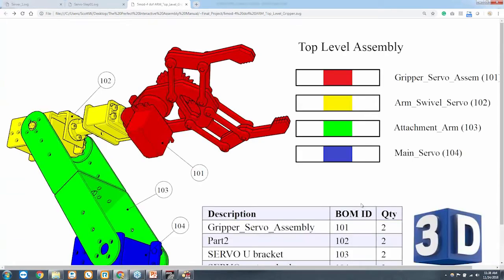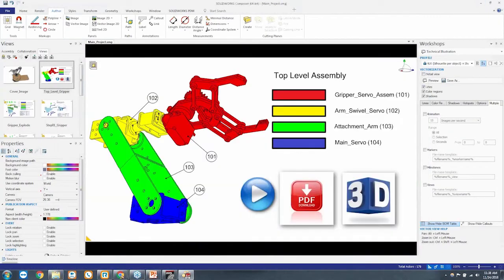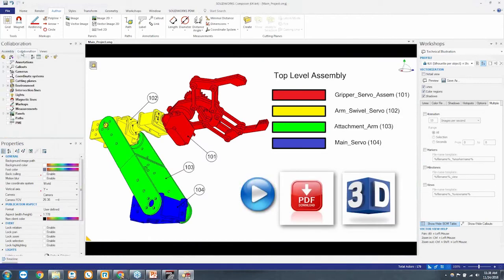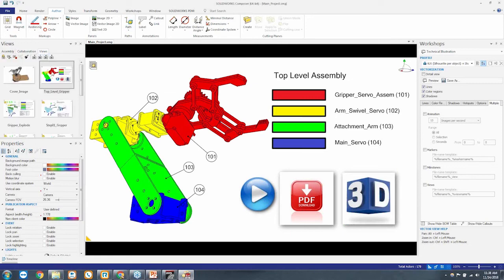Okay, let's back up here. That 3D PDF is kind of hiding behind the build materials here. But I don't want to publish this out again. I'll just show you if you ever have this happen to you. I had my BOM table still checked, and that's why it showed up. Uncheck that BOM table, resave it out, and it won't be there, but we'll skip that step. In that 3D PDF, it would just link you to the rotatable one I already showed from SOLIDWORKS. Okay, so on to the fun stuff here.